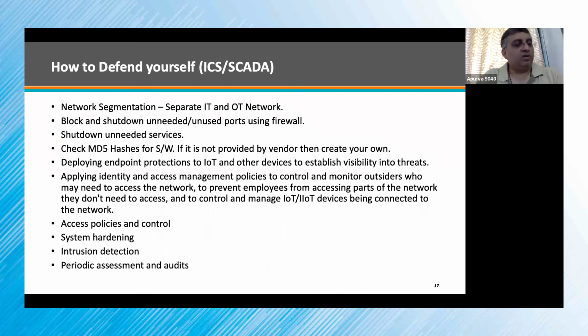So how do you defend your SCADA? Why am I talking more about SCADA? Because of Industry 4.0, eventually the manufacturing systems are all about industrial control systems. Hence, I am talking more about this. When you want to defend your SCADA, please separate your IT and OT network. You have to have separate network segmentation.